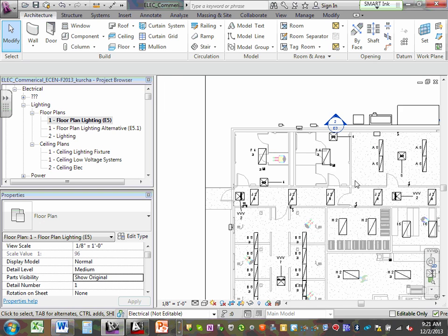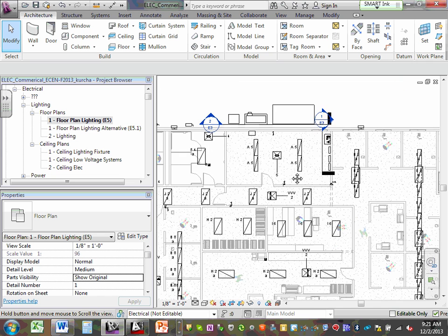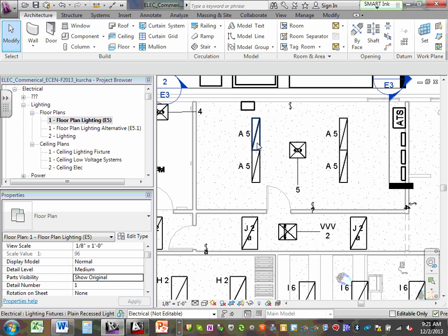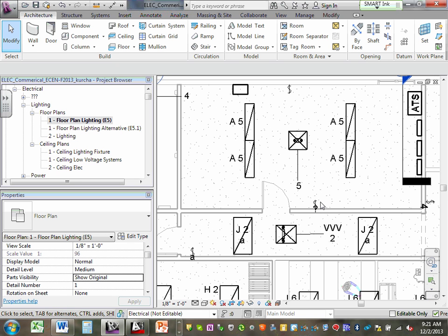All right, so let's go directly into this mechanical room. Let's see what you did here. You have circuit number 5, Matt, right? Everybody can see, guys, Matt has circuit number 5 here for all these fixtures in the mechanical room. What type of switching do you have, Matt? Can you see that? You have a high voltage switch that needs to be labeled. Is it a low voltage switch? No. It's a high voltage switch, the control. It has to be in a relay.